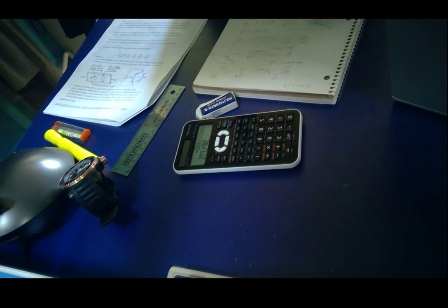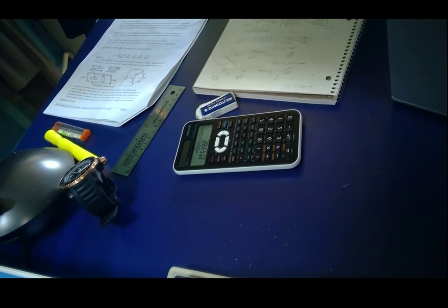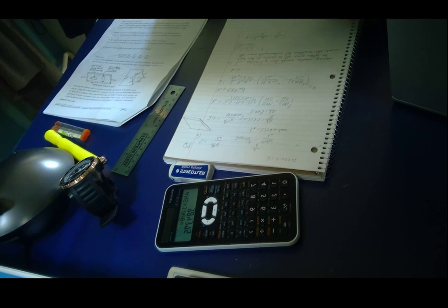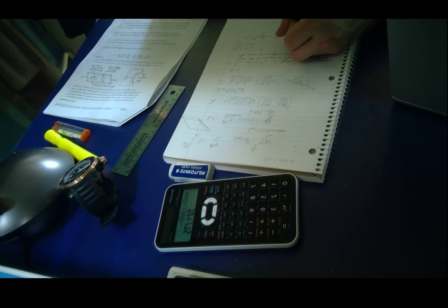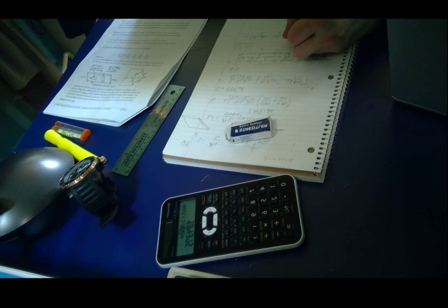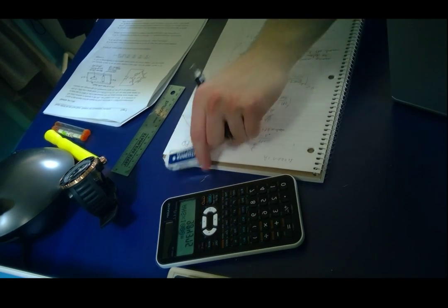And of course, because they have the same initial R, they will cancel because it's exactly the same metal, exactly the same temperature. That means that it is going to expand in exactly the same manner. And so the RT cancels, and we are left with our strain only caused by the stress. That's how it goes. So V out is equal to beta times R. Well, I'll put strain instead of stress, because the strain gauge just measures strain, not stress, divided by R. All right.